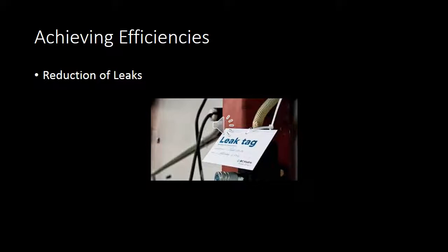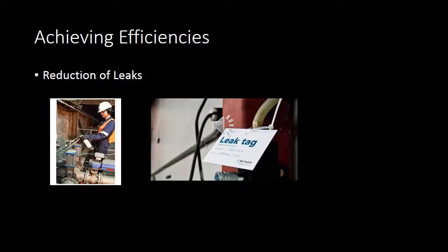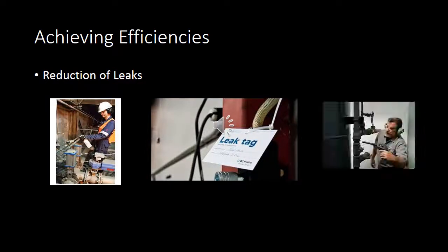Leaks cause an increase in compressor energy and maintenance costs. Quick connect fittings always leak and should always be avoided. In addition to increased energy consumption, leaks can make pneumatic systems or equipment less efficient and adversely affect production, shorten the life of equipment, lead to additional maintenance requirements, and increased unscheduled downtime. A simple way to detect large leaks is to apply soapy water to suspect areas. The best way is to use an ultrasonic acoustic detector, which can recognize the high-frequency hissing sounds associated with air leaks.